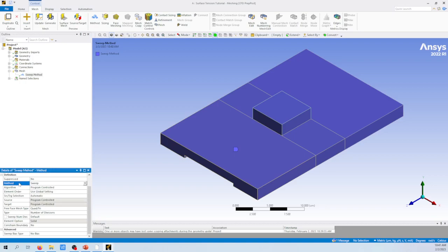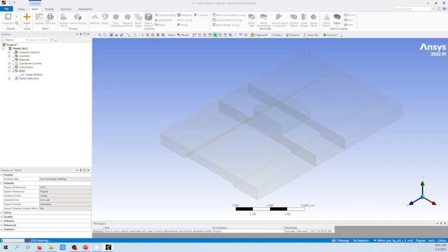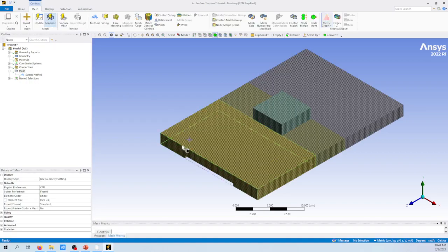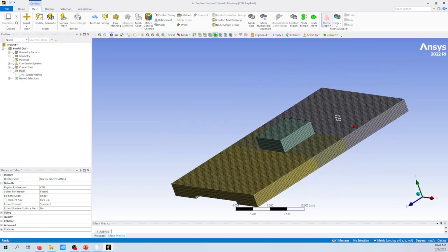Now this sweep is going to give you perfectly cube elements, quadrilateral, hexahedral. So just using the default is all right. We can mesh it. Now, do you see how fast that was? That is only because we did that to the volumes. And you get a beautiful mesh.